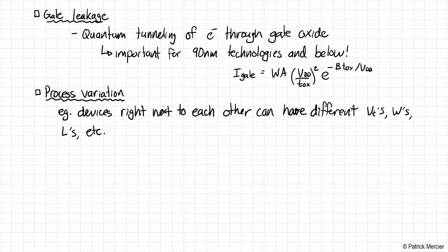So you normally design your transistor for, let's say, 1 micron divided by 45 nanometers or 50 nanometers, and when it comes back from the foundry, it has limited accuracy in terms of its lithography and so on, and it can't guarantee that it will be 1.00000 micron wide and 50.00000 nanometers long. There's going to be some variation on that, right? Maybe it'll be 1.05 micron by 53 nanometers, something like this. And then the one next to it also won't be the same. There's going to be some variation.